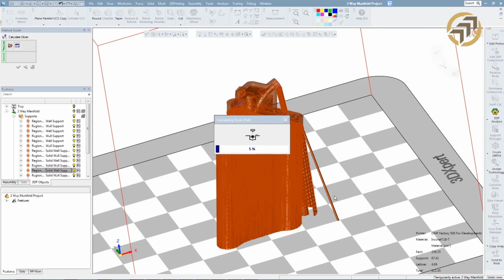It allows you to create virtual 3D volumes and assign specific build parameters to it without splitting the part. This allows you to define special build parameters for thin area, concentric slicing, and rough slicing without forming a weak point in the part. Offloading calculation allows you to add slicing machines in a private cloud to which you can offload the slicing and enhance slicing speed dramatically. If you want to hear more about any of these topics, please contact us after the webinar.